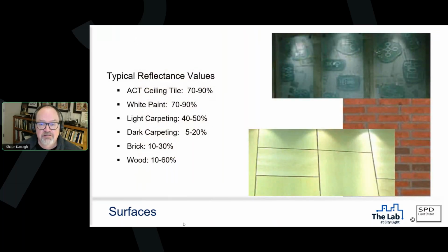understand that the reflectivity of surfaces may not be what you think they are, right? People think, for example, that wood surfaces reflect a lot. This maple that you're looking at here from the Reebok World headquarters, I'm going to say that's 40 to 50% reflective, right? Brick, much less. Acoustic ceiling tiles, a really good one, maybe 90% reflective. So you're absorbing a lot of light no matter what you have, but the surfaces getting the light onto them, at least revealing them. You don't necessarily have to bounce light off of them, but revealing them is critical.